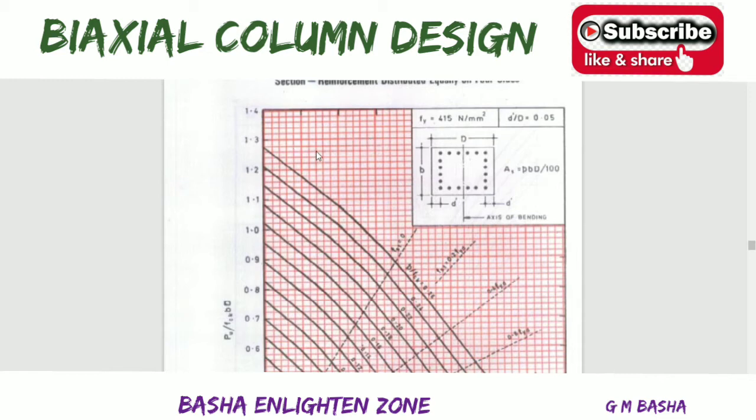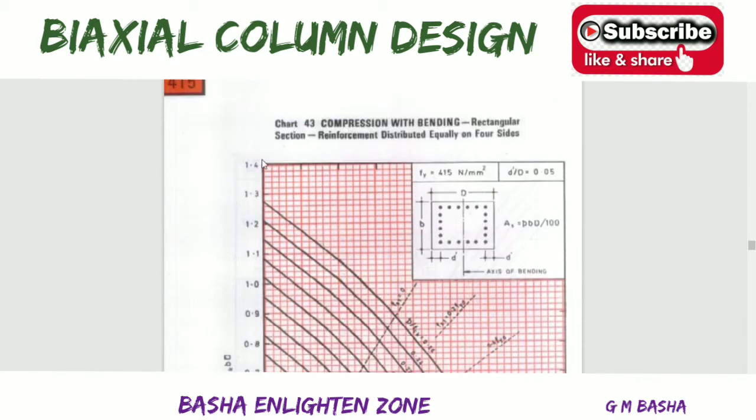So what are the minimum conditions required for selecting a particular graph? See here, this is the graph of chart number 43. So compression with bending, a rectangular section, reinforcement distributed equally on four sides. See here, distribution will be equal here, so if you observe clearly, reinforcement is distributed equally on all four sides.